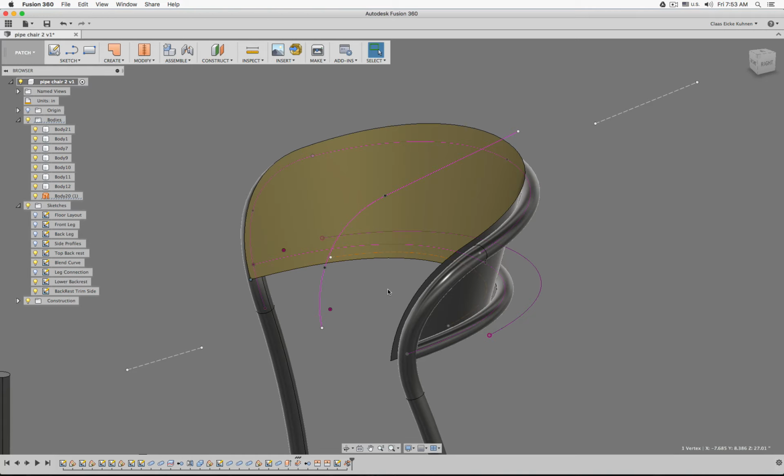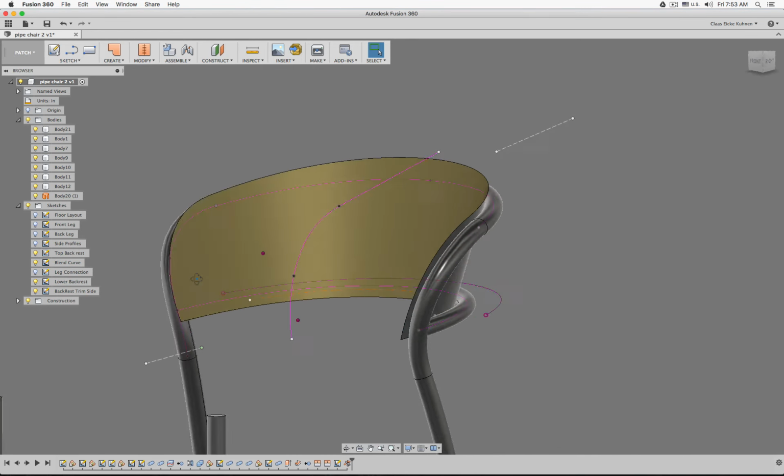I could round this one inside the sketch. I would have to draw this accurately, but this is honestly way too much work, and then I have the rounding detail inside the sketch, which is kind of stiff. And if this is a solid object and I can round just a vertical edge, I can always change the fillet radius, or delete the fillet command, so I'm a lot more flexible with it.